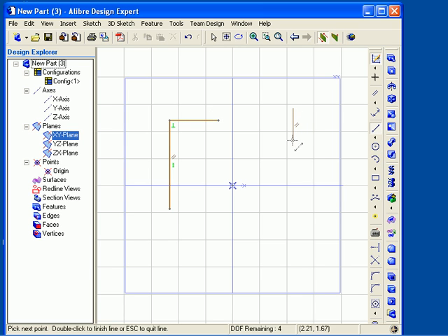Once you've begun sketching the figure, if you hold down both the Control and Shift keys while sketching, the constraints will no longer be inferred when you design your part. If I release the keys on the keyboard, the inferred constraints can return when creating a new sketch figure.